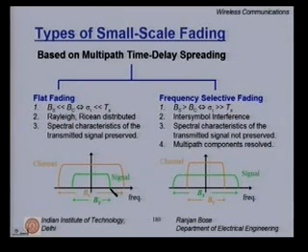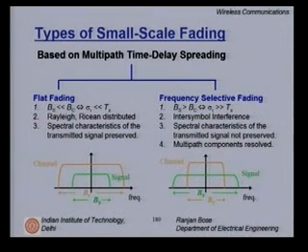We go for the next dimension, which is the time dimension. If my channel is slowly fading or fast fading, I can transmit copies of the same signal at different time durations separated by more than the coherence time, so that they will undergo independent fading. Or maybe I can use multiple antennas and use some kind of spatial diversity, so that I can overcome the effects of fading. Clearly, frequency diversity will not work in this case.